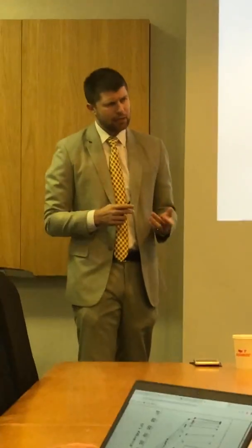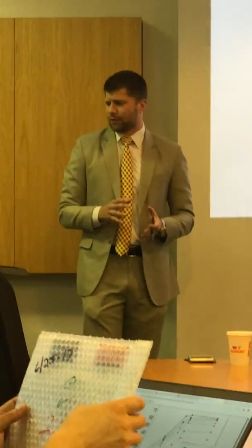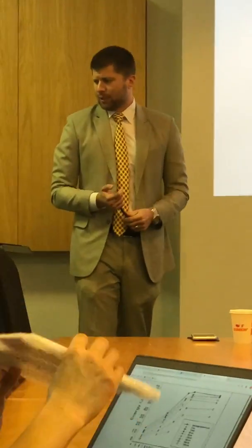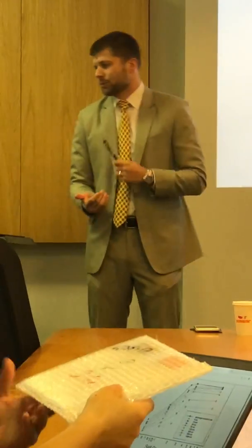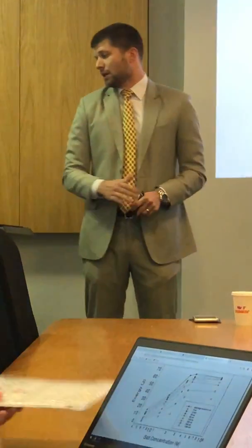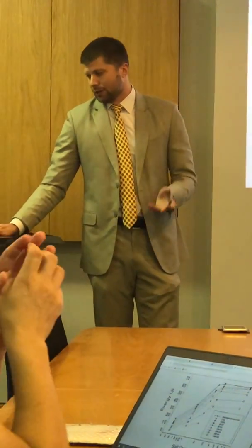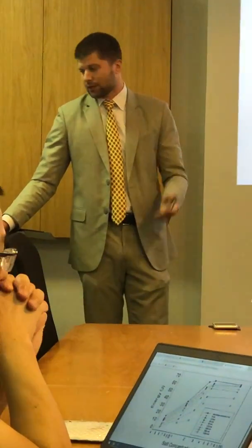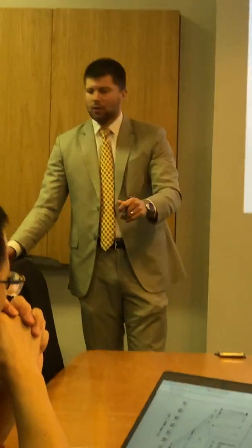So there was this delta, and next I dug through literature and found earlier work where people had figured out the impacts of ambient temperature, current density, ionic concentration of electrolyte, absorption coefficients of the anode and cathode materials, concentration, intercalation material, and the electrode material, the electrode's mass, its density, porosity, thickness, a whole bunch of other variables that go into developing one of these devices, and their impacts upon a whole bunch of variables that very quickly can replace those experimentally derived terms in my Randles ECM.